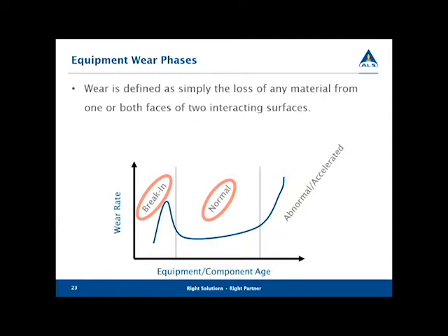Normally, obviously, if we have normal wear during that phase, that's typically going to be attributed to a compromise of the film strength between the things. And quite frankly, normal wear occurs mostly during startup. When we're in a startup position, when that machinery is at rest and goes from rest to moving, you're going from two surfaces that are basically almost in contact with each other, and most of the time the asperities might be contacting each other, to when that lubricant film gets established. That in between is where wear occurs most often.